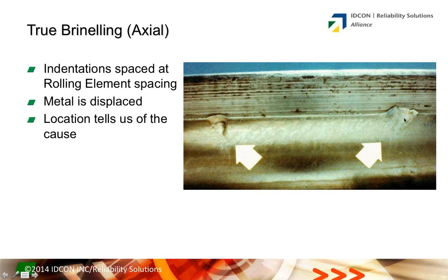How did that damage occur? We could have dropped the motor on its end, but that's not likely. The most likely cause of this is somebody beat that bearing on with a hammer using an incorrect procedure. So the location here tells us the cause.